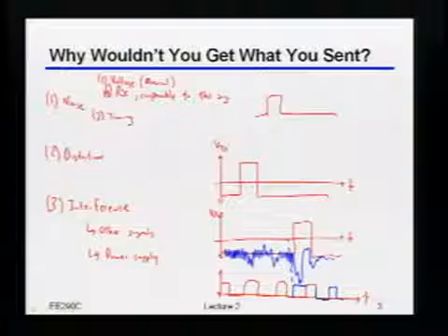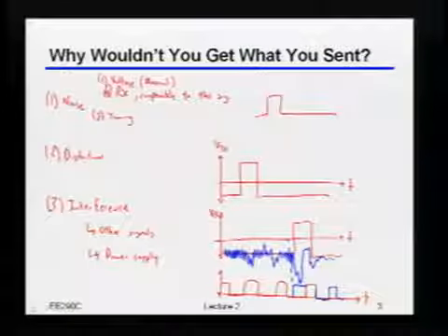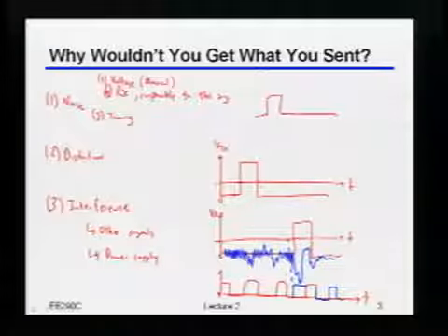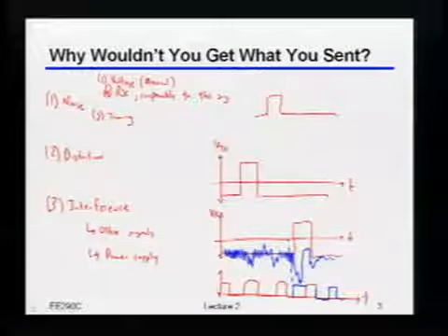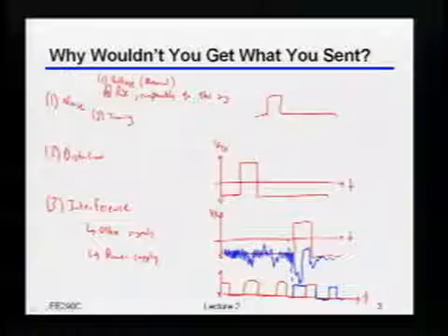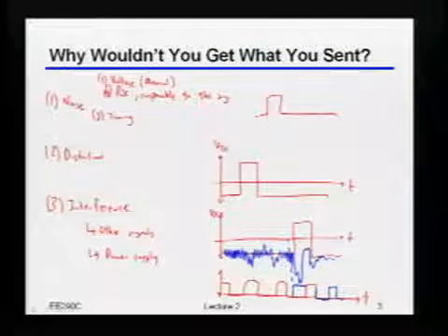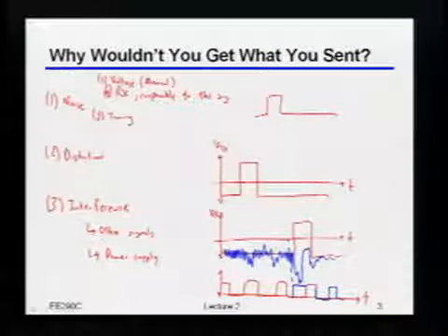Okay, so there's amplitude to phase conversion. What do you mean by that? So if you have voltage noise and say you have a transition on your signal, then that ambiguity in your amplitude causes ambiguity in time. There we go, exactly.